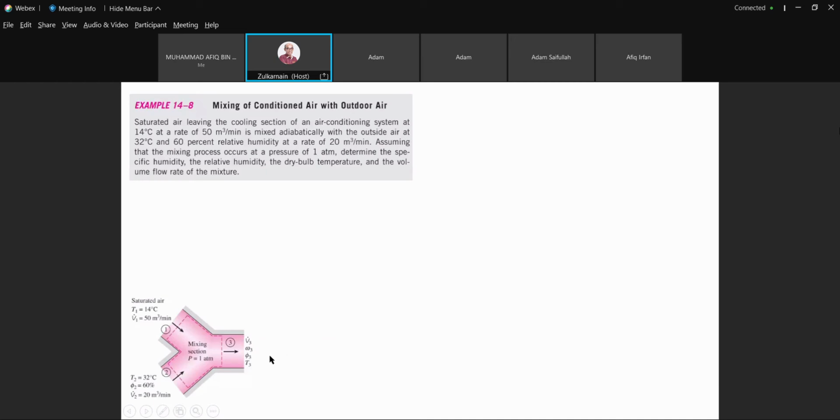Right? So if we have that type of section, then we could have another process or another state in our psychrometric chart. I will look at the past year's question, which has a cooling process that is more relevant to our country. We mix two flows, becoming M3, and then we cool it, coming out at state 4. At state 4, we put it inside the room for the air conditioning system. Okay?